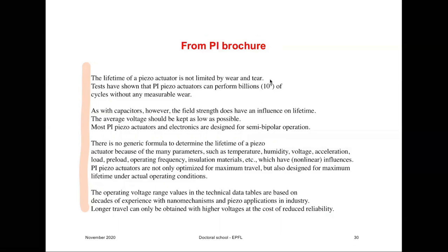You have to be careful if you are using very thin elements, tape casted actuators, then the capacitance is going to be very large. And if you have 100 of these layers, then the capacitance of the whole actuator can be really very large, and that can make it difficult to drive it. Your power supply also has to supply the current, because by applying an electrical field, the actuator also acts as a capacitance, and you have to charge that capacitance, so you have to provide high current.